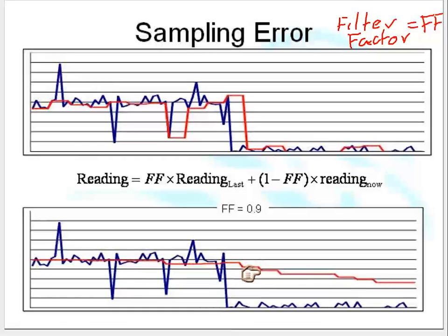And the next time round, it's going to say, oh yeah, there's 80 odd kilograms on that belt. And there's 65 odd kilograms on that belt. And there's 55 odd kilograms on that belt. So filter factoring is basically lying. It's giving false values at the PLC end of things. And if we have a catastrophic failure, a sudden, immediate failure, the filter factor will say, oh no, everything's fine, the belt's still got stuff on it.